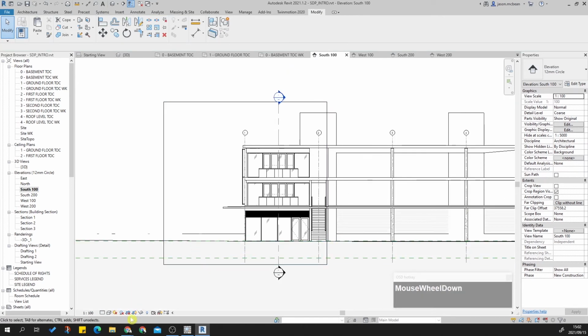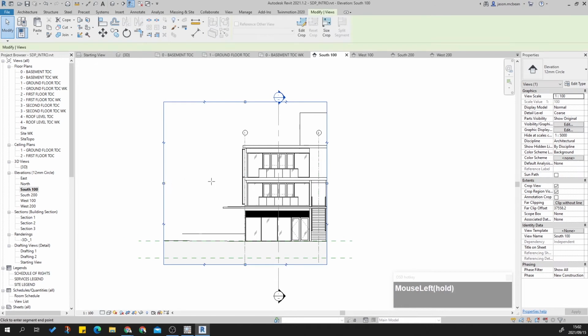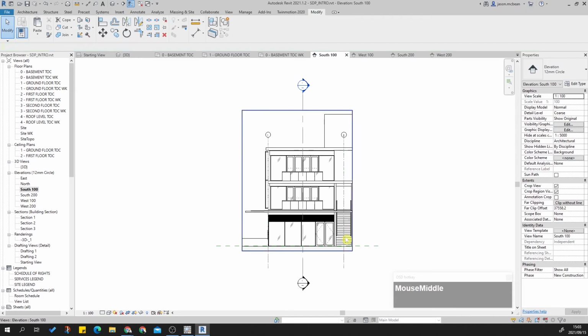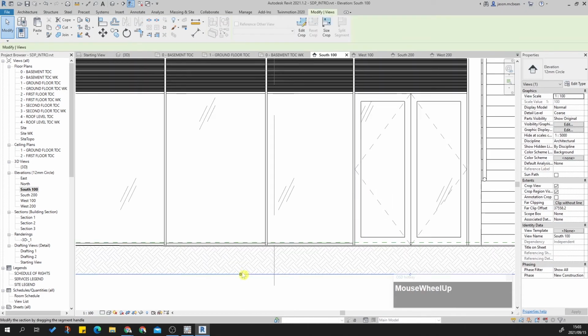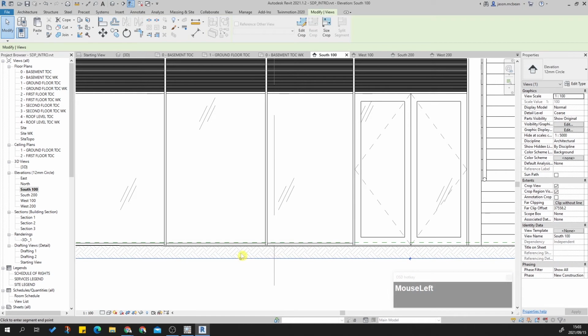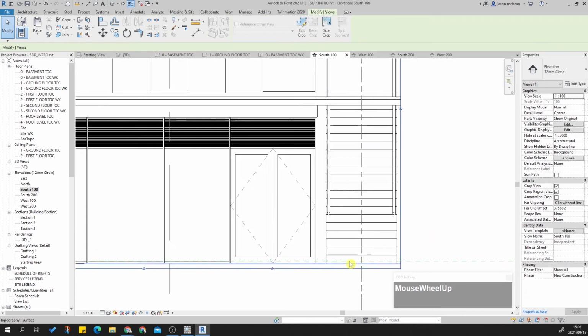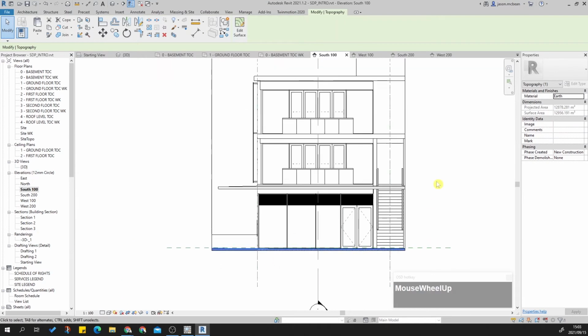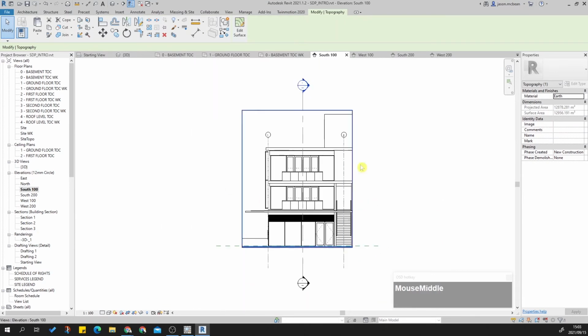Let's pull the crop back on. Let's pull this close. That's good. Now these section markers sometimes do get in the way, so just move them out of the way because we will fine tune this stuff. Okay, that's good. Grab this last one, get as close to that line as possible. We use detail line work here, and it's not a true section. I'll switch this off because I know that there's a step in front of my shop front as well, so I'll switch that off and we'll detail that later on, but for now, perfect.